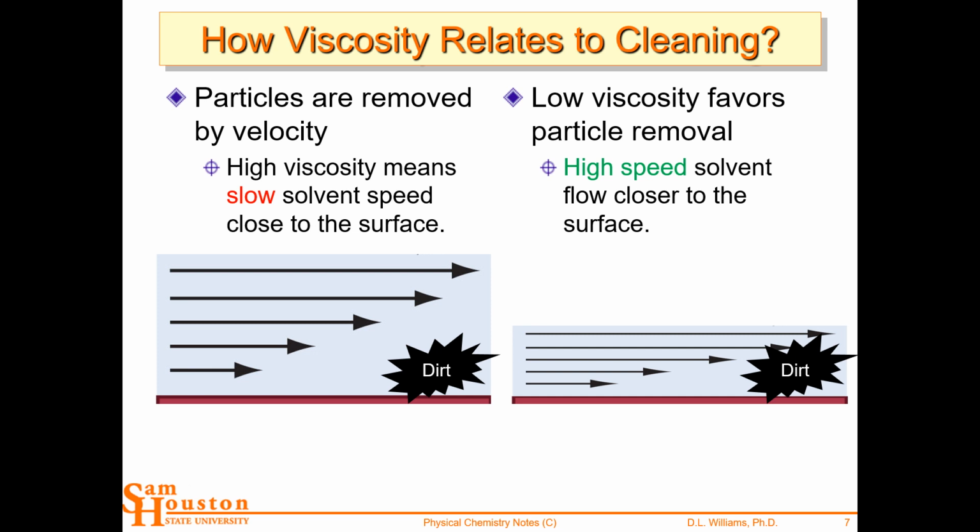Density also knocks particles around because the solvent carries some mass with it in a small volume. So density is favorable and viscosity is disfavorable. So we want a low viscosity, high density solvent to push molecules or push dirt off the surface.